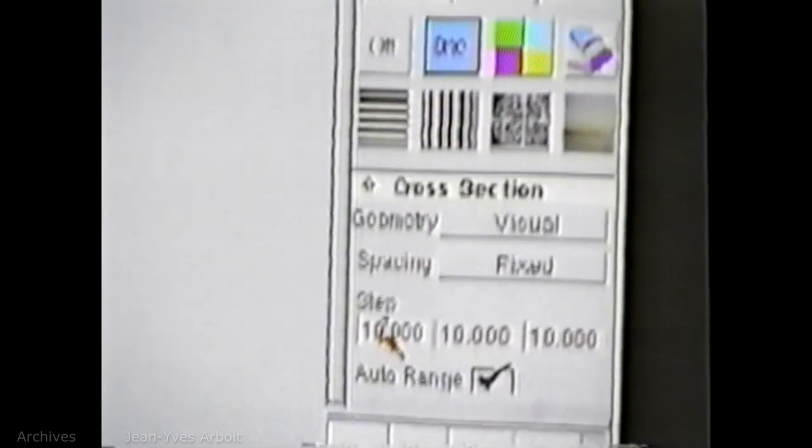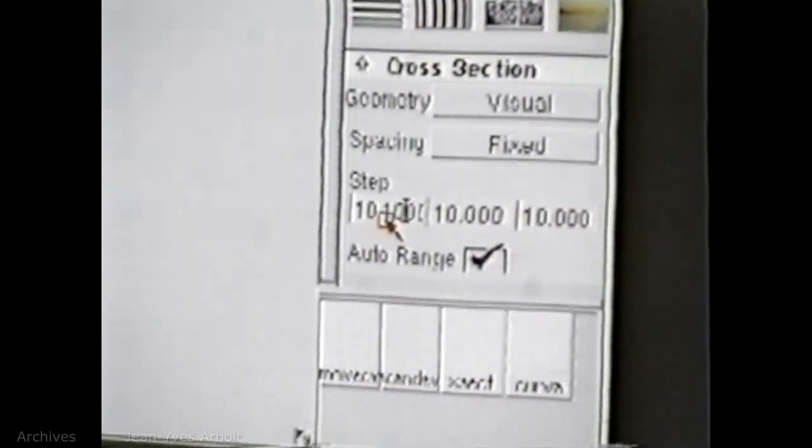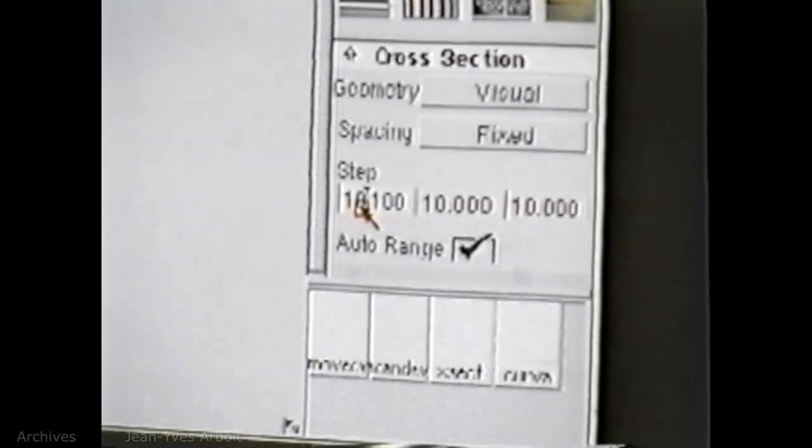So for instance, if I pick these surfaces here, this is a lister that allows you to go through and pick any of those surfaces, so you can have one individual surface. Then we can turn on the CVs and put on cross-sections. I hadn't set up my cross-sections. I want 100 millimeters, or 101 again.